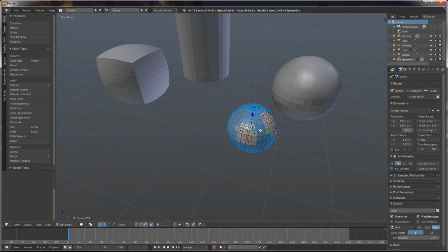There are times when we need to move our objects around in 3D space. In order to do so, we need to know about the axes in Blender. If we look in the lower left-hand corner of the 3D viewport, you will notice an icon which shows the axes. The blue axis is the Z-axis, which is the vertical axis. The green axis is the Y-axis, and the red axis is the X-axis. The easiest way to move objects is with the Translate manipulator.